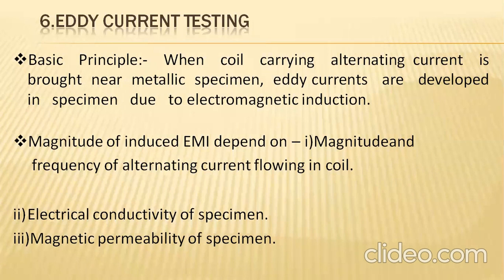And particularly in the case of this electromagnetic field, the AC power supply will be passed, and due to the passage of this input current, eddy currents will be produced only at those defect areas due to the variation of the magnetic fields. So in that particular area, the magnetic field diversion takes place. That makes it very easy for us to examine the currents. That's the basic concept in the eddy current testing process.